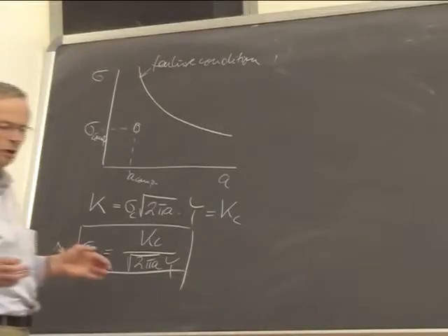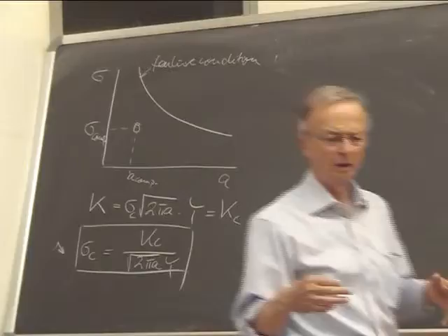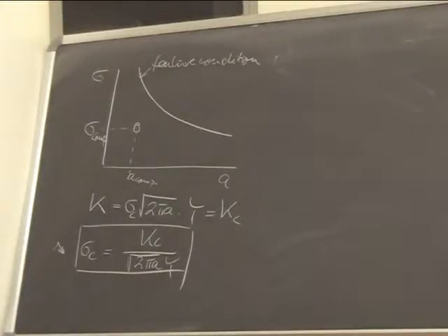Not only in the design stage, but also when something is already in operation. You find a crack, but nevertheless, your structure now has an age of 20 years or 25 years, and you scratch your head and ask yourselves, what would happen if I found a crack here at the critical location with high stress, and what is the crack size that I can find, and what would then be the remaining lifetime?